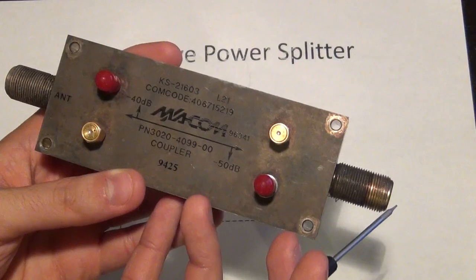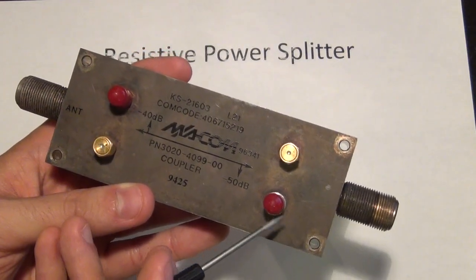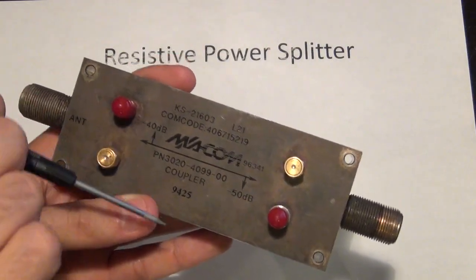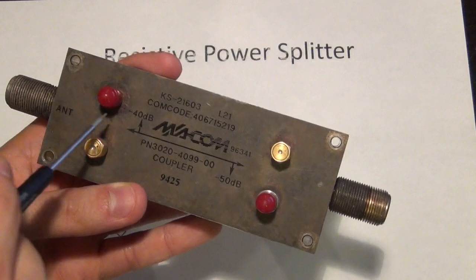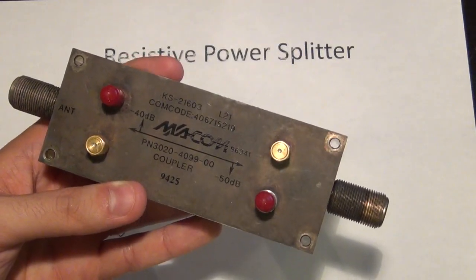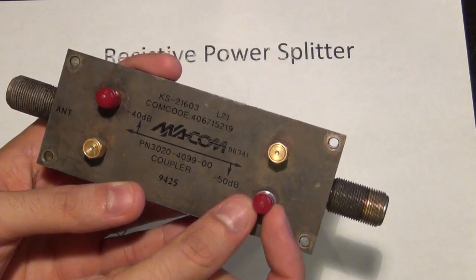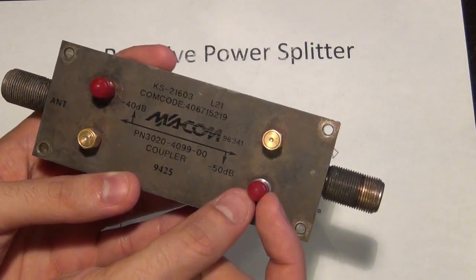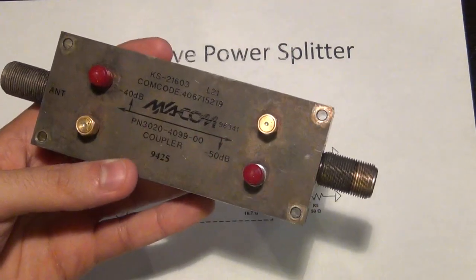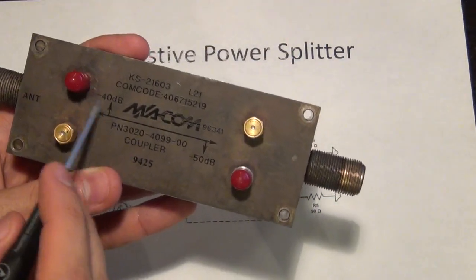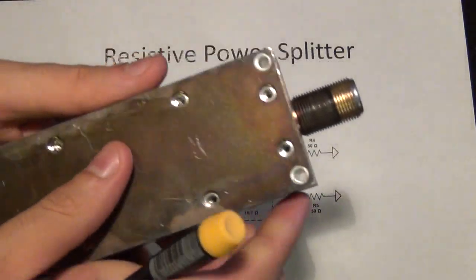So if I put in 0 dBm here, minus 40 dBm comes out of here, minus 50 dBm comes out of here on the return path. So on the forward path you get minus 40 dBm, and if I put in 0 dBm on this side, I get minus 50 dBm on the other port. This coupler is used to just sneak on the signal a little bit. If I want to just look at the signal just a little bit, I don't need to take half of it away. I will use a coupler like this. Now, because the attenuation is so large, it's minus 40 and minus 50, the construction of this is really interesting.